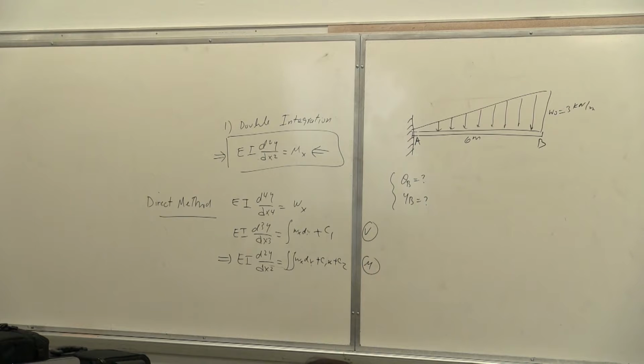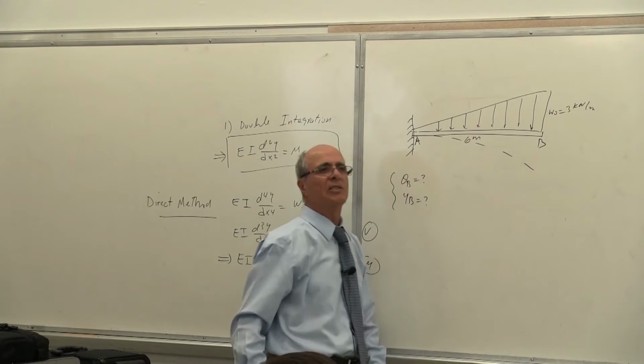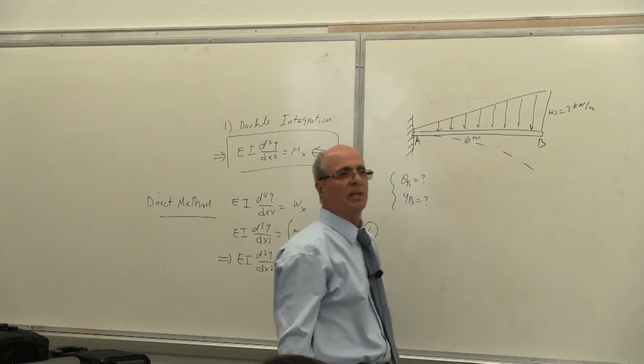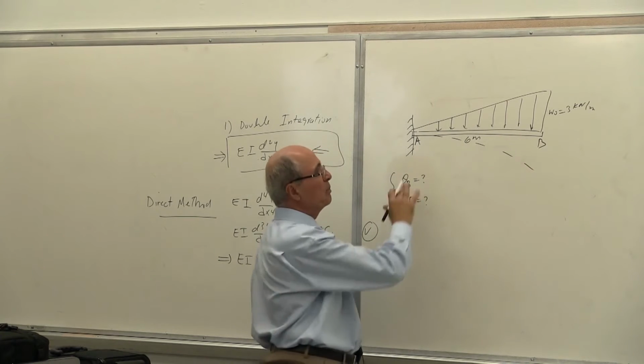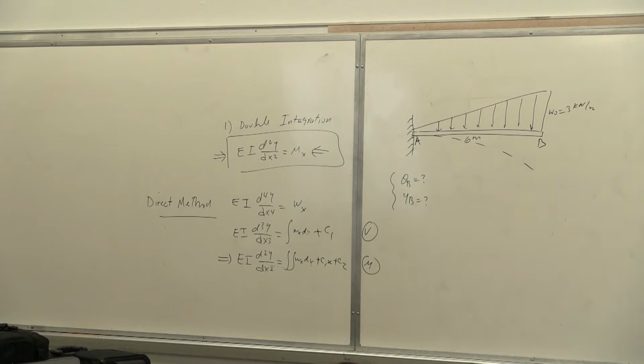At the end, because this beam is going to bend. Here, this is a fixed support. Everybody appreciates that the beam is going to bend like that. So you have here YB and theta B, and in between the same thing, but that seems to be the maximum. And usually we are looking for the maximum, correct?